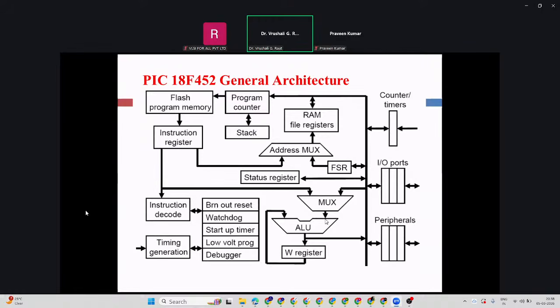And what about the other part coming for the operation to the ALU? It is coming from this MUX. This MUX can select from this bus, or it can be from the instruction. Whatever data is in the instruction will come here. Externally we can take it from IOs, from counters, from peripherals, or internally from the memory part of the instruction, whose data will come out here.